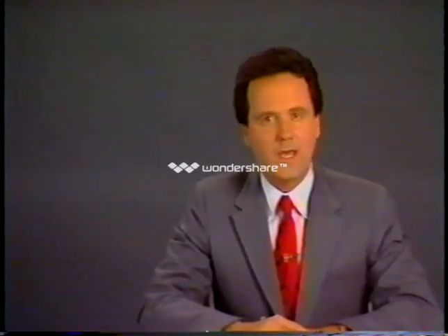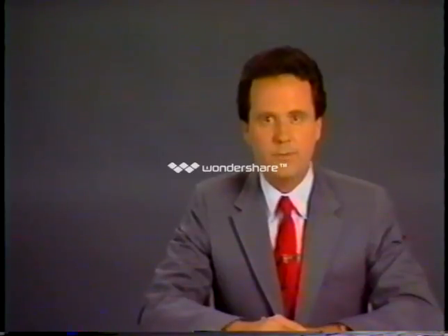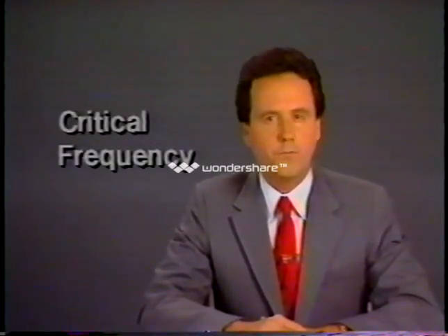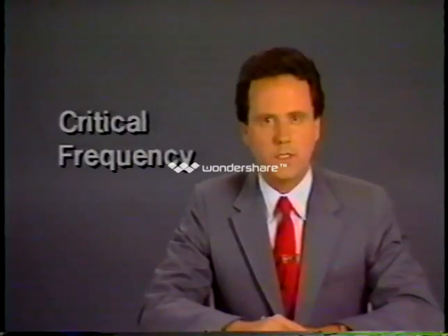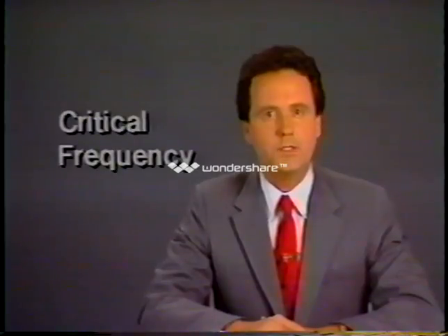A control loop may have many components, and the combined actions, delays, and responses of all of these devices determine a natural loop frequency, or critical frequency. This is also the frequency at which the loop will tend to oscillate.